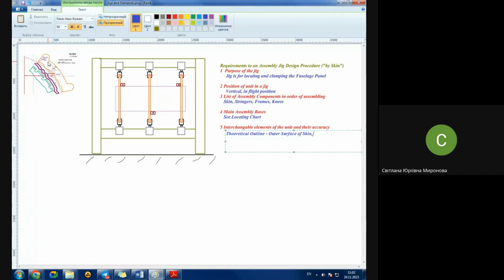Accuracy. No, people, I have no plus-minus sign. Let it be 1.8 millimeter, for instance. If it's a passenger aircraft, here we suppose it to be plus-minus. Minus we will add. And what next do we have? Next are BH, base holes, diameter 5H7. Base holes with diameter 5 and accuracy which corresponds to the 7th level of international accuracy grade.